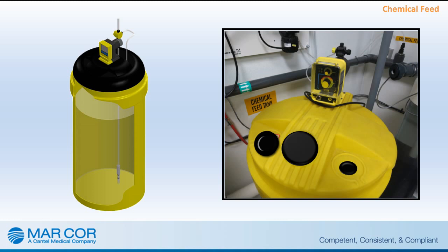Automatic controls and monitors can get out of calibration and need to be checked, and the pH may be tested from a sample port after the chemical feed pump to assure the appropriate pH is being met. This testing may either use a pH test strip or a pH meter.